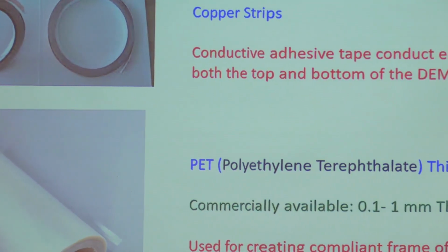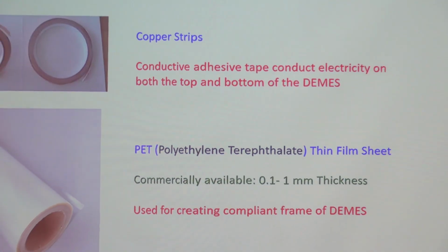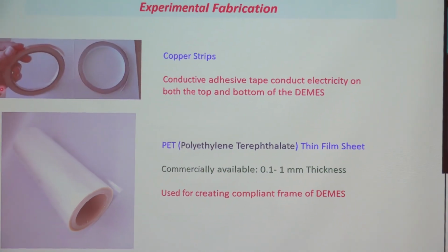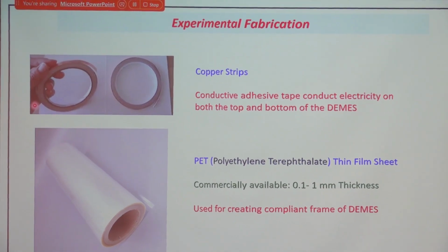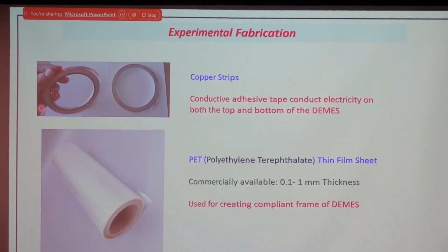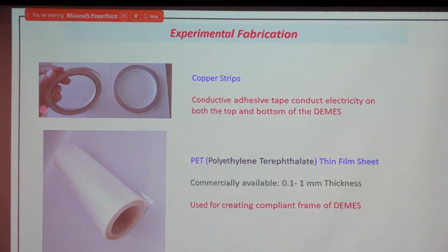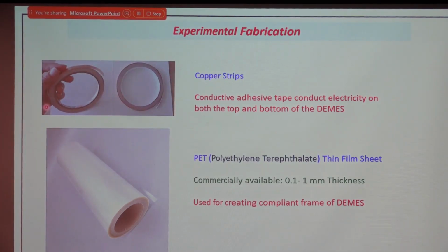So usually what you see, the failure will take place at the joint of that copper strip with the active area. At that particular location, the failure will take place. The reason is, first thing is, again, it's an intersection point, okay, and when you are supplying it, initially it will get generated, or it will reach that particular location, it is basically going to spread out. So that is a more susceptible area.